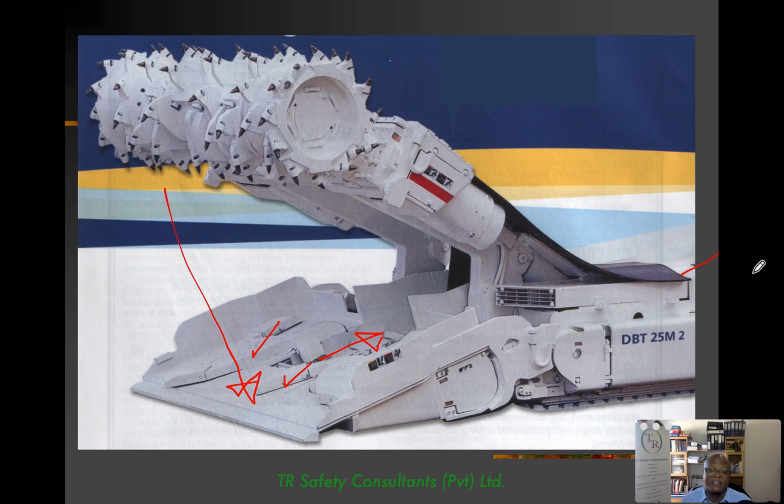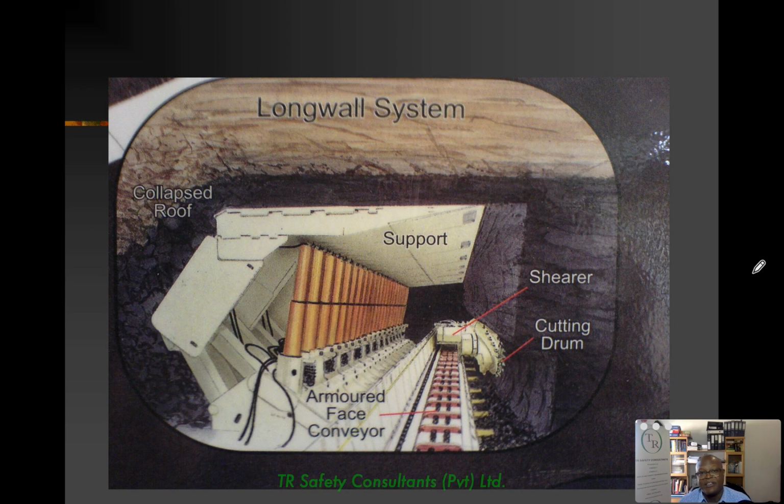Even the shuttle cars, you find they've got a spooling cable at the back, and they go back and forth, so it unspools and spools, reels and unreels around. Even the employees and everybody else who walks underground are told, if you see the cable of a shuttle car working on one side and you're walking on the other side, you don't straddle it, because at that moment it can jack up, it can whip up, and you don't want that between your legs. So employees are normally taught to step on it as they go across.